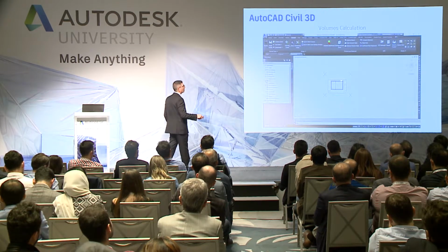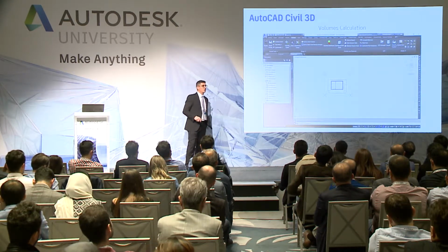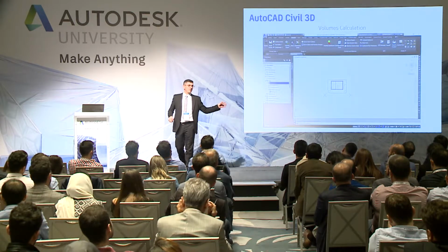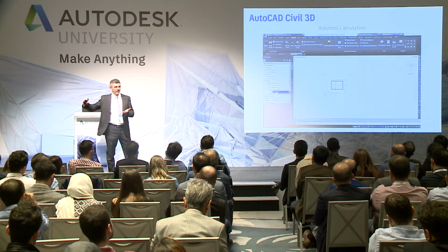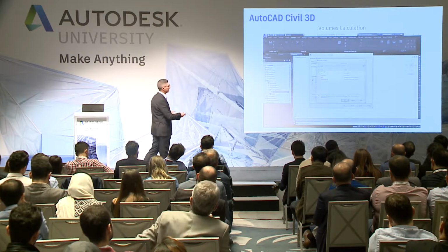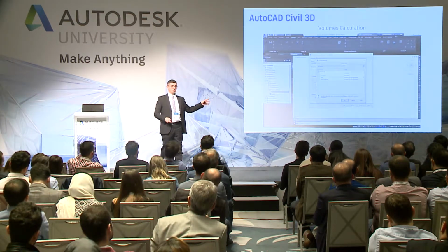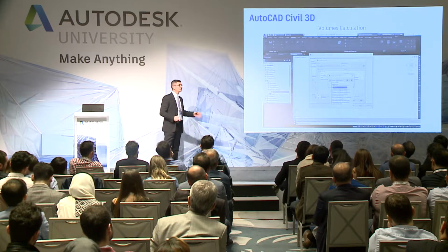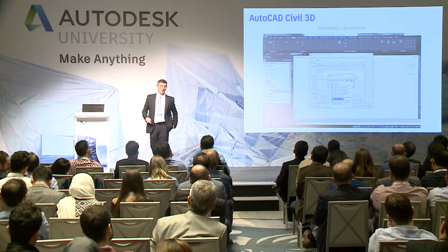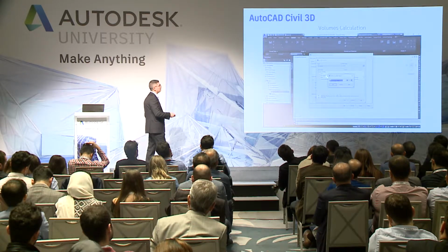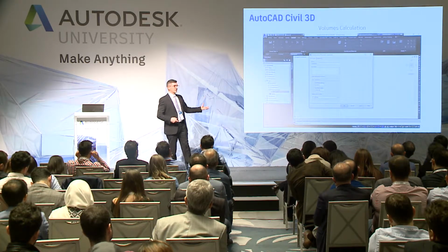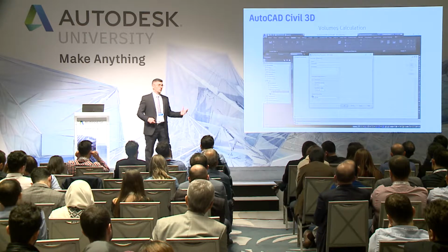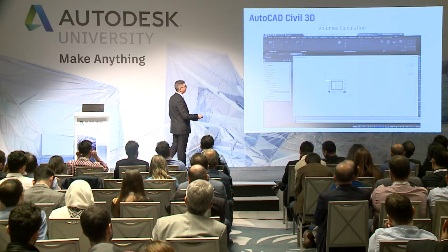In this video, I have also changed one side, because the excavation can be different from side to side. We can also have a transition from one elevation to another elevation, OK? This type of excavation is very easy, to be honest, but we can manage many complex shapes. Here, I start to create the surface that I need to understand the volume of my excavation. Then I can start to set the name.